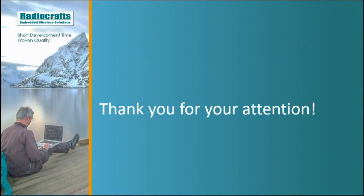We do have listen before talk in the system, but because we are running quite high data rate and each packet is quite short, we believe that we will be within the 1% duty cycle limitation, which is required for Europe. We do not currently support frequency agility, meaning that we don't move frequency in case it's noisy, which you would require for the polite spectrum access according to the CE and EN 300 220. Hope that answers your question.